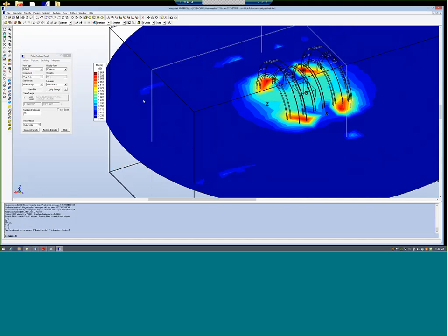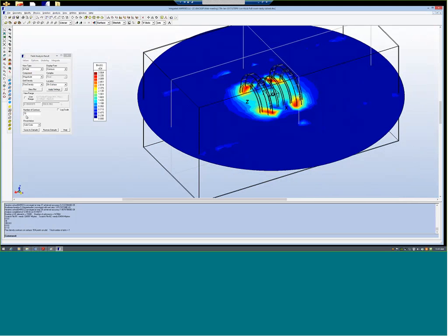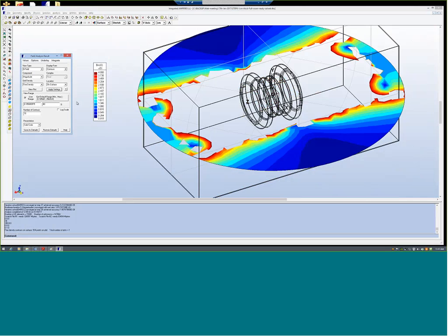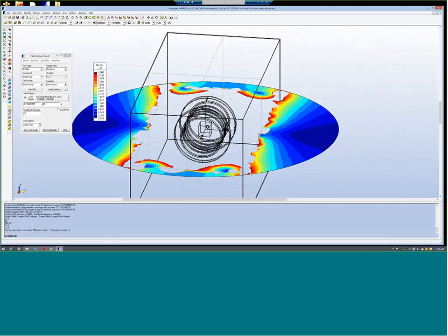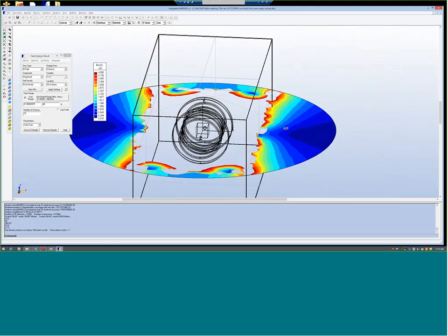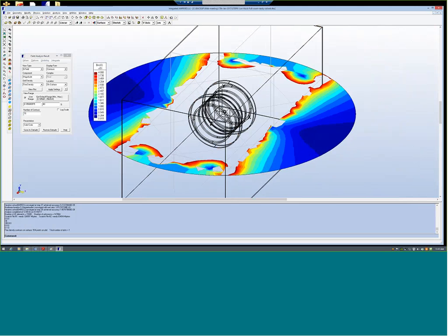Okay, inside it has got 3.5 Tesla. It is a coarse plot; you should have a finer grid. So outside, let's see. Let's give the 40 Gauss. Yeah, okay, that's good. Now if you see this, 0 to 40 Gauss, you are getting, that means near to the wall still the field is large. Similarly here, this part has got very small, like 1.6 Gauss.